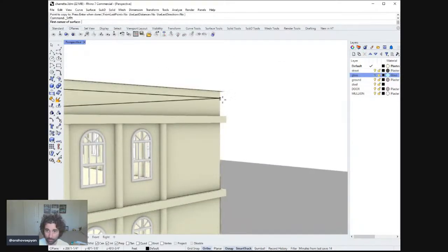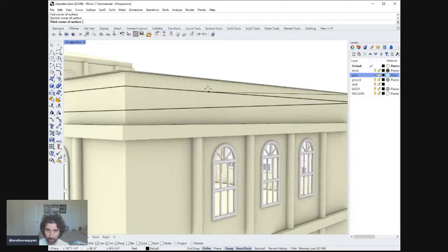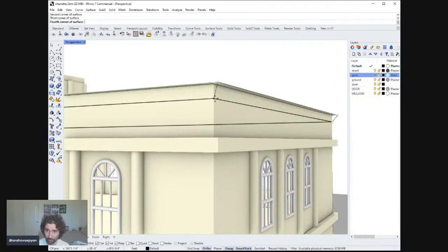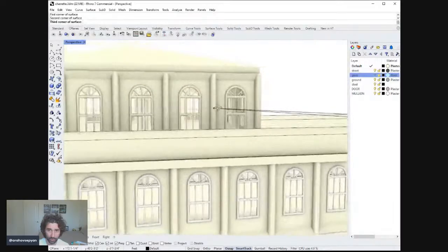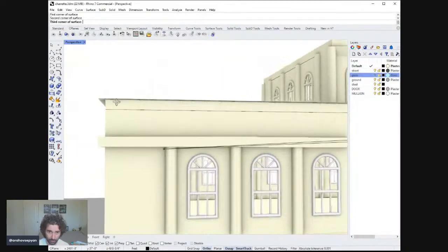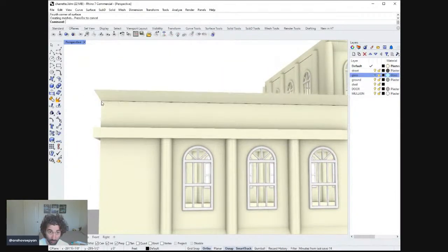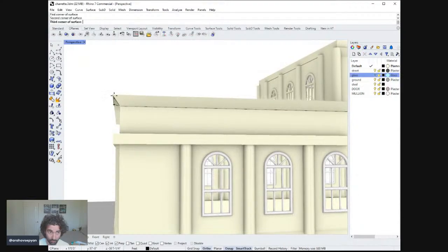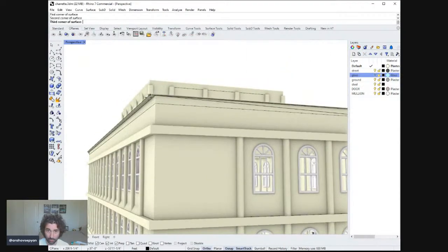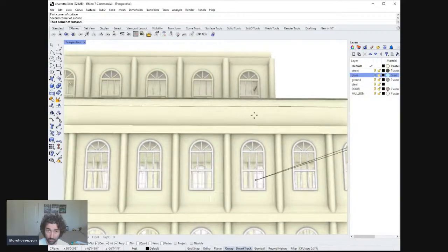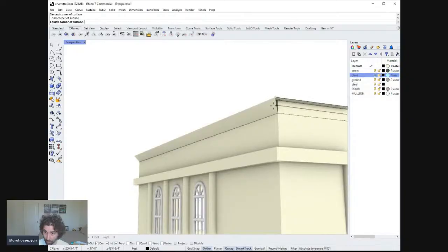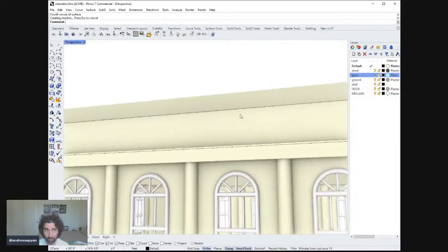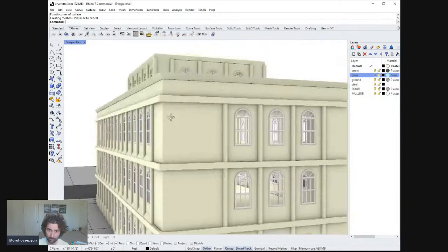And let's give it a cornice, right? Let's give it what modern architecture forgot. We forgot our cornices, and that's why you have to put a flashing detail every time two different materials meet each other, because we build everything out of wood now and we don't do cornices. So we gotta put sheet metal inside and fold it over and put it everywhere two surfaces meet each other, because otherwise it's gonna leak everywhere. Because we don't build things out of stone anymore. We don't do cornices anymore.